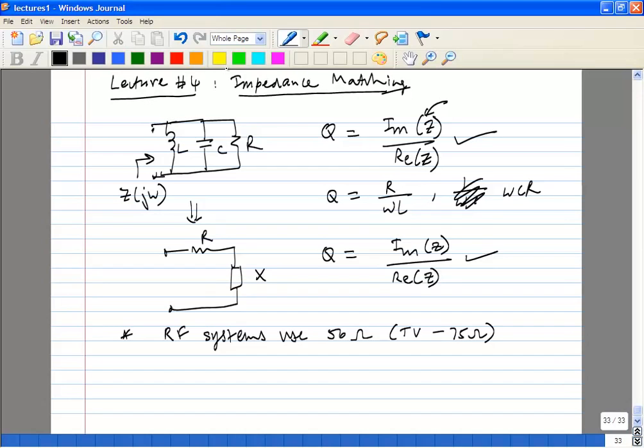So what that means is anytime you interface, for example, from the IC to the external world, you have to match the circuit to 50 ohms. Now, of course, the other thing is, it so happens 50 ohms is the approximate trade-off between minimum loss in the system and your max power handling. It happens to be somewhere in between. So that's the reason why people chose 50 ohms.